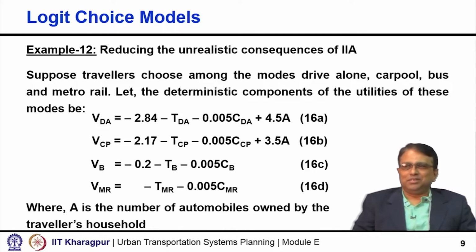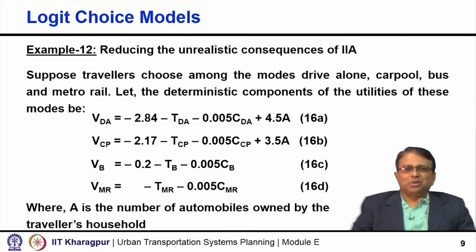So, the increase and decrease of fare or travel time or travel cost, that component of the result, the probability of using that mode, that will be logical to you, as we have seen here that the fare is increased, so the probability of using that mode is decreased. But because of the IIA property, where people are shifting or where from people are shifting may not be very, very logical.